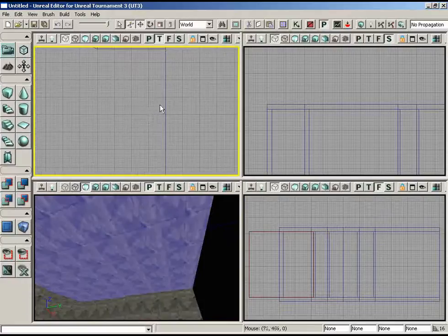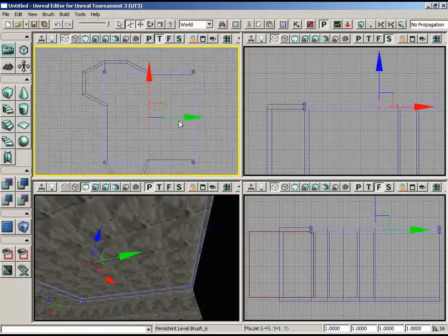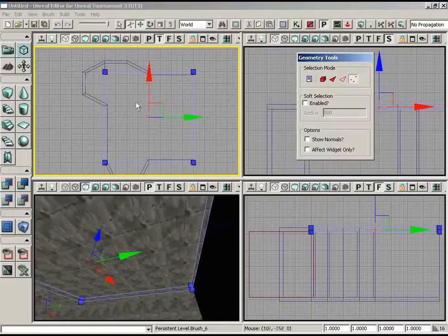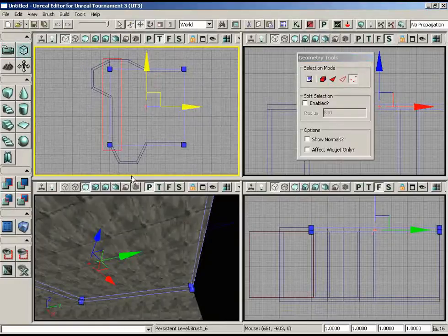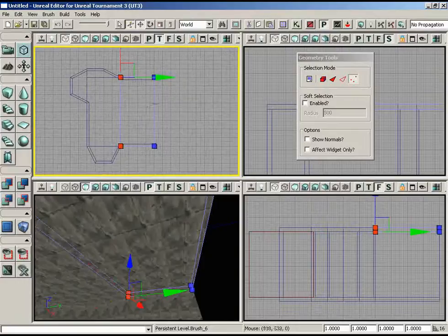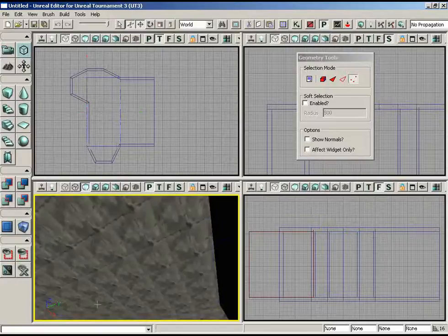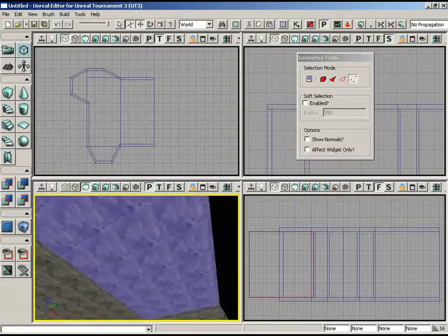So I'll begin with the entire ceiling, and let me edit it a little bit so that it's only half the width. I'll jump back into geometry editing mode so that I can select two of the vertices on one side and drag them in so that the width is half of its original. So now we're at the exact half of the floor. Because then I can select the entire brush and Alt-drag to duplicate, and now we have two different ceiling pieces. Let me rebuild geometry so we can see about how much space those are taking up. So we've got two separate pieces now.